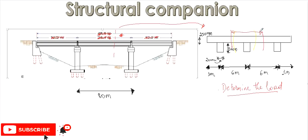If I cut from here, this is 3 meters, and here also this is 3 meters. So the portion of the slab which is resting on this beam is 6 meters.